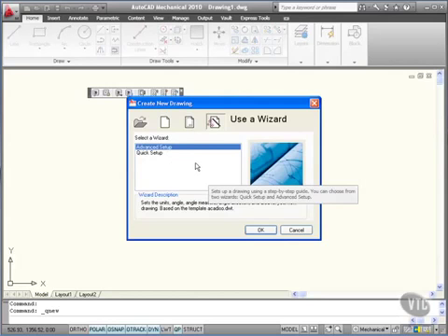So you can see that startup dialog there is very useful. It's actually been around since AutoCAD 14, and the startup variable has also been around since then. So remember, when you first install AutoCAD Mechanical 2010, type in startup, set it to 1 so that you can switch on your startup dialog box.